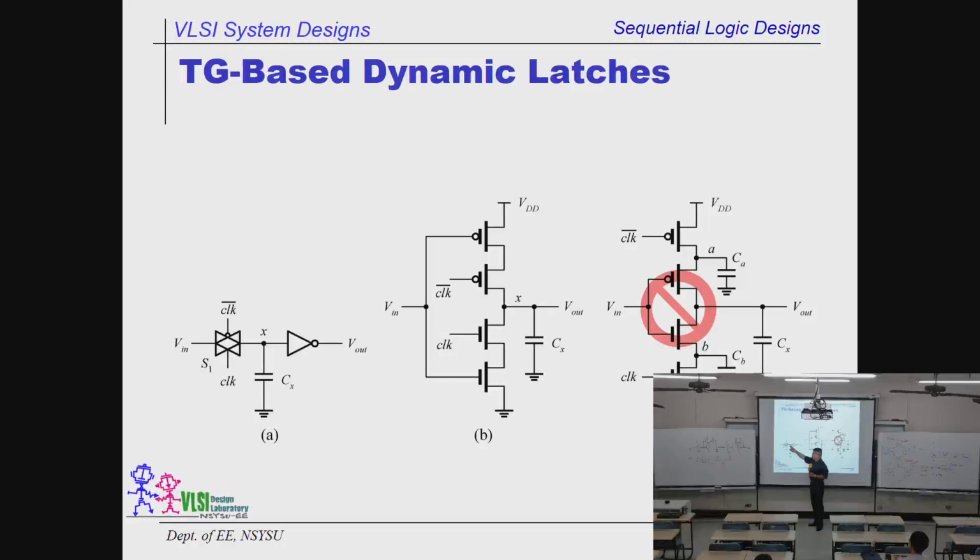When there is a leakage, the voltage here will go down very fast, so that the original high signal will become low after a while. If you don't take any action, then the logic value here will be changed from high to low. If you want to keep it longer, you got to have a very big, fat capacitor here to keep it longer. That is a price you have to pay, and that we don't like, all right? So you either have a very high-speed operation, or you got to have a very big, fat capacitor to help you. All right, anyway, this is just a design.